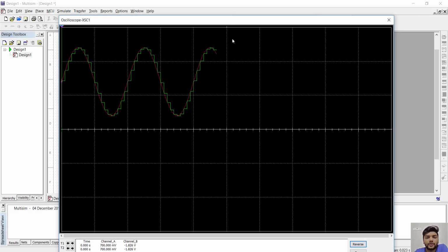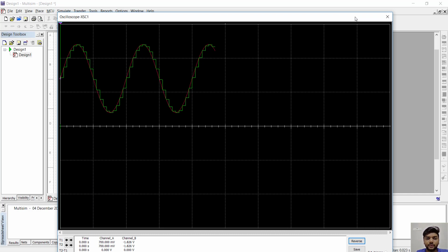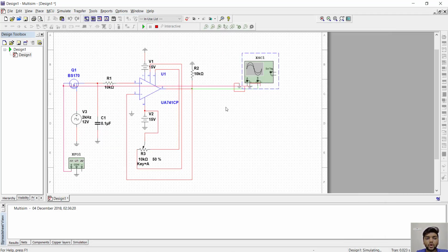So, to get a more accurate result, if you increase the duty cycle of the clock voltage, you will have your sample signal following the original signal and then giving you an accurate or similar signal on the output side when you connect the sampling points. So if you want an accurate signal, you are either going to increase the clock voltage duty cycle, or you are going to increase the number of samples being taken in a single cycle.